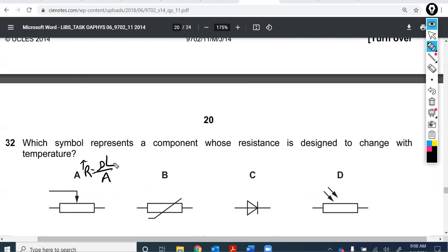And so that's just another chance to review this idea. Greater length, greater resistance, more resistance, dimmer light, right? Less current. All right. Let's be careful about saying that, less current. So there'd be more voltage dropping across this at more resistance. If it's a series circuit, right, then the current's going to be the same everywhere in that series circuit.